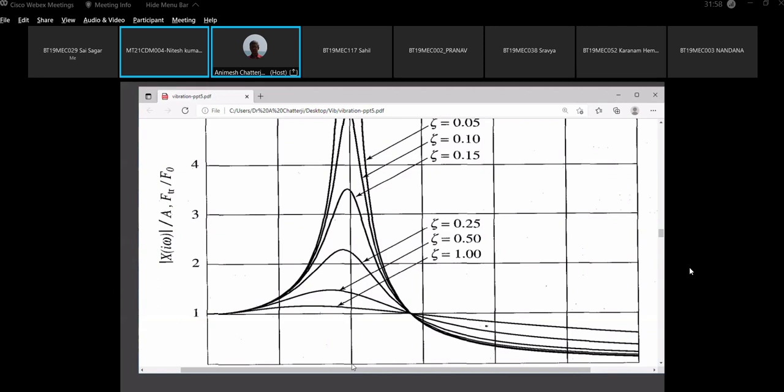That is why we buy springs in the market. You buy a spring and then you cannot say it should not compress. We want compression, but at minimum, because if compression is more, then it will reach the solid length.